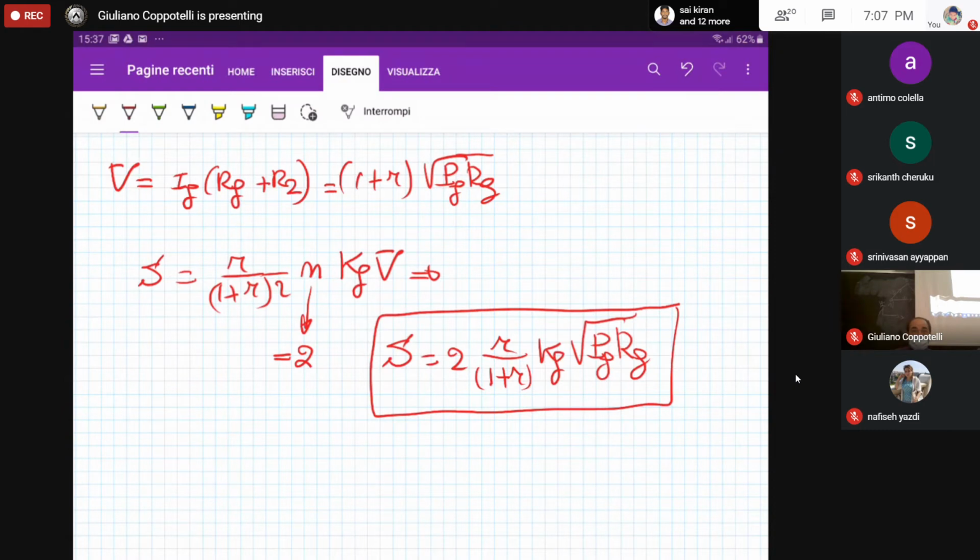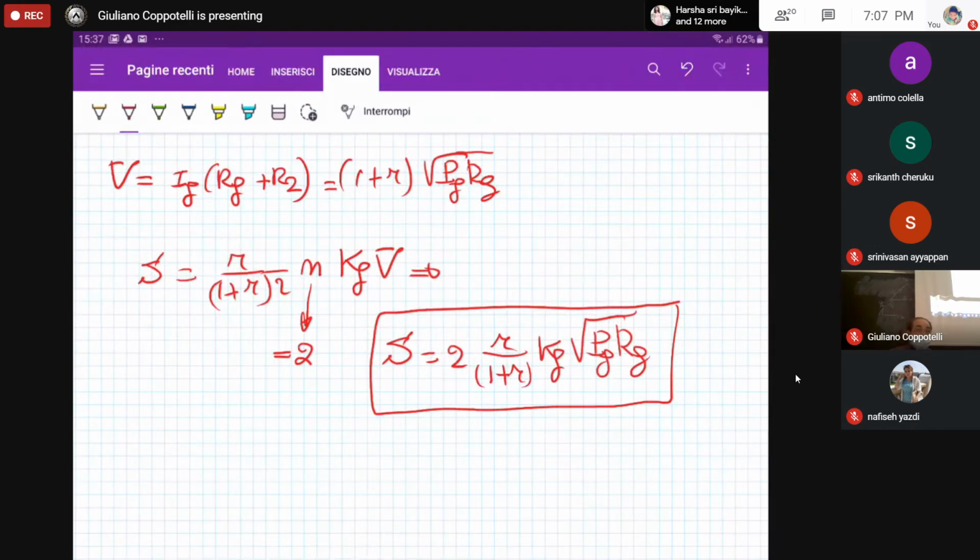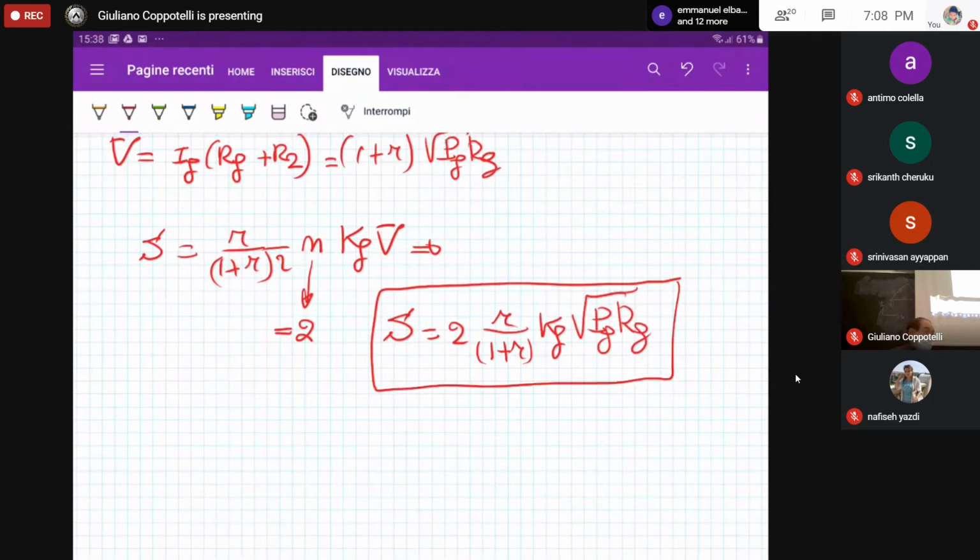Okay. So what is the general operating condition when considering the Wheatstone bridge for strain measurement? You have first to remember that you are measuring the strain in just one point. You can use 1, 2, or 4 strain gauges at the same time for measuring the same strain, so this strain at that point. The closer the strain gauges are bonded, the better the measurement, the higher the accuracy, because you are measuring the strain through the change of resistance due to the same strain.